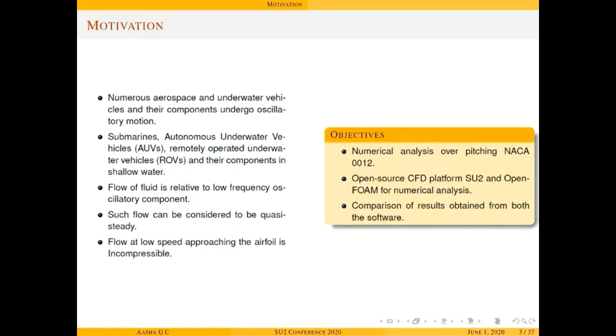Our motivation to work on this topic stems from the fact that there is a large number of aerial and underwater vehicles and their components that undergo oscillatory motion. For example, submarines, autonomous underwater vehicles, and their components in shallow water. We decided to focus mainly on the pitching aspect. Fluid flow is the relative low frequency oscillation component, and the flow can be considered quasi-steady. Flow at low speeds approaching the aerofoil is incompressible.